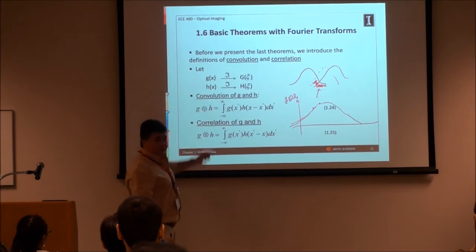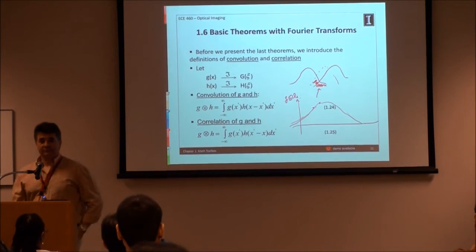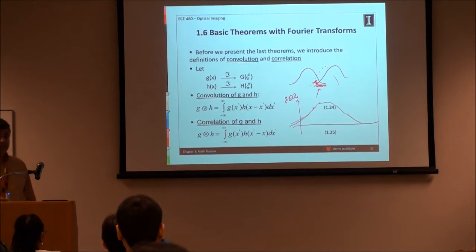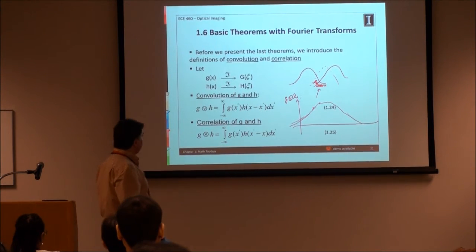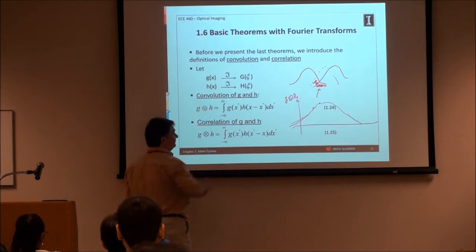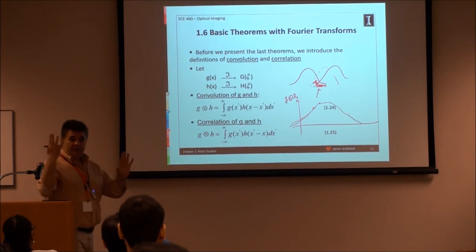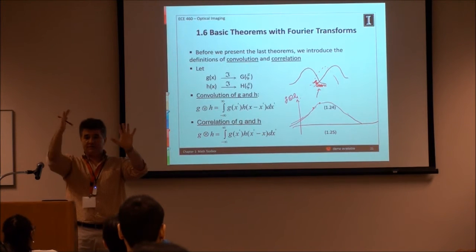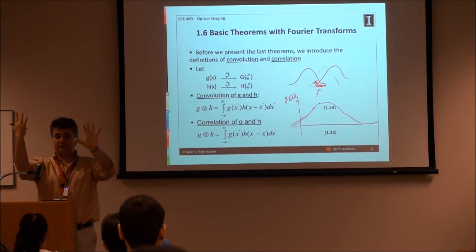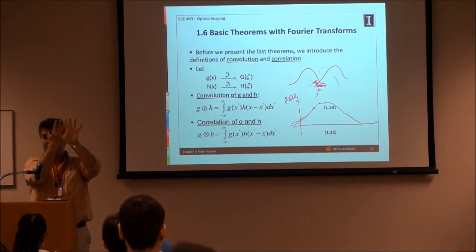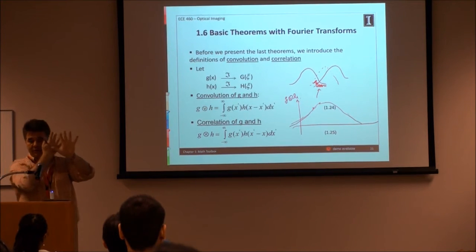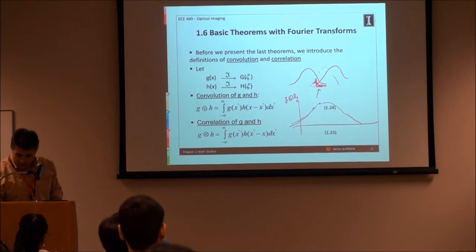And this is my notation for convolution. We keep the cross for cross correlations and the V circle for convolution because convolution has a V in it. That's easy to remember. So you see the meaning of this? Convolution means I flip one of the functions, I translate it, and at each point of translation, each coordinate, I multiply and integrate, which means I calculate the area of overlap.